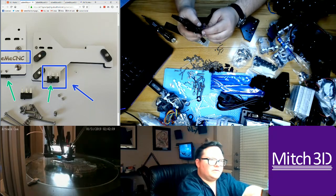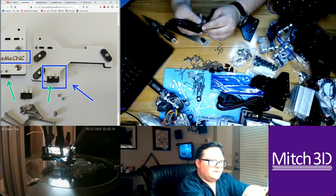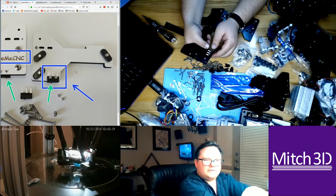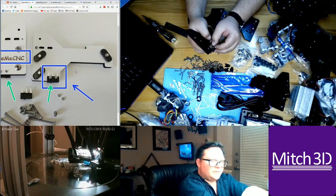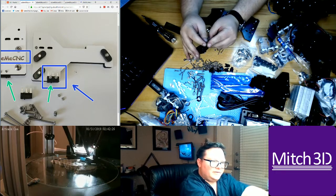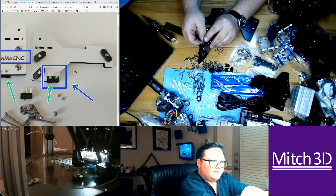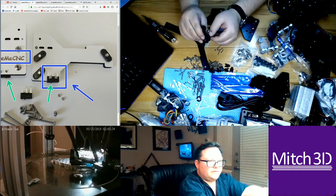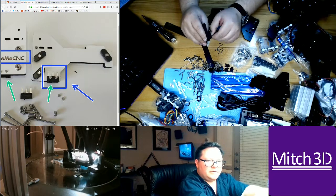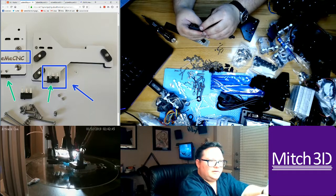So these have quite a bit of, what do you call it, give. So I'm going to try to keep them all pressed up against the parts. I think the problem is you're getting a lot of your precision from laser cut parts. As long as the end stops don't move at all, you should have pretty good precision, and as long as your arm length and your delta radius and all the other stuff is precise.